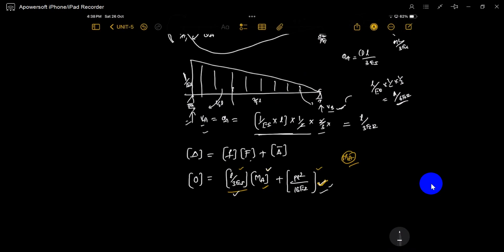If there is no MA, this much rotation will occur. If MA of 1 per unit moment is generated, this much rotation will occur. How much moment is generated so that it balances exactly this much rotation? Understood? That's why the final displacement is 0.